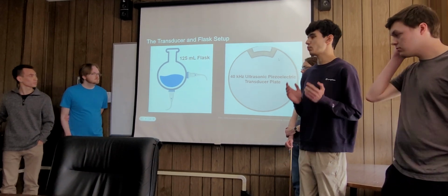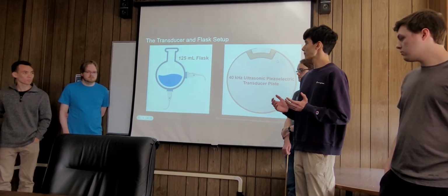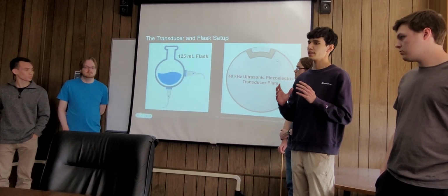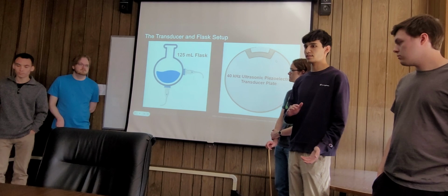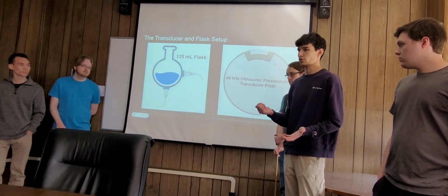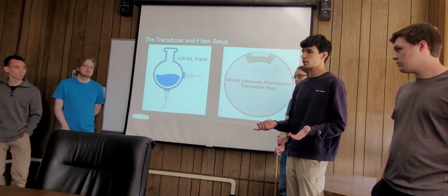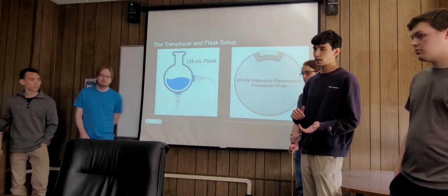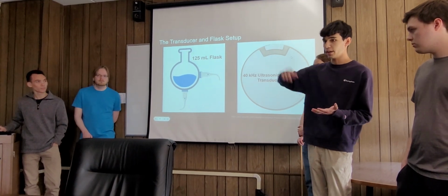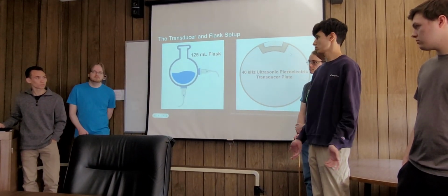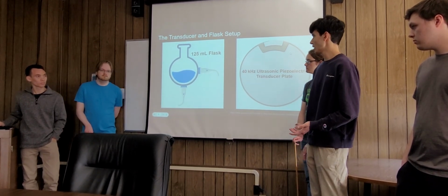The other key word though is we need pretty intense acoustic pressures for the cavitation to happen. So what we can do is use the resonant frequency of the flask. It's in that system. So typically it's between 25 kilohertz to 27 kilohertz, and that's in the ultrasonic range. That's why we need the ultrasonic transducer. But then we drive the transducer at that same frequency. So let's say it's 27 kilohertz, we drive the transducer at 27 kilohertz also, and that will make the amplitude of those pressure waves that we're transmitting in there even greater. So that will let us have a better chance of actually cavitating the bubble inside the solution.